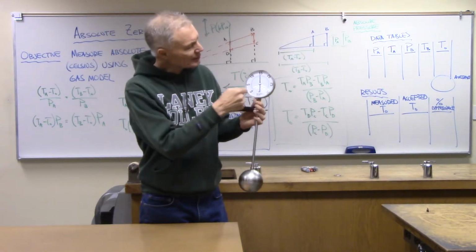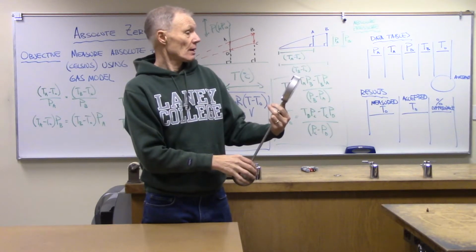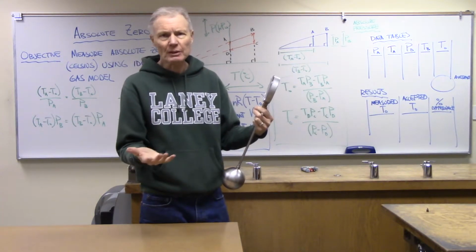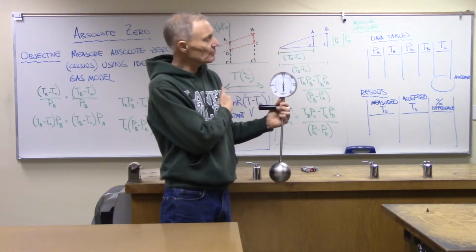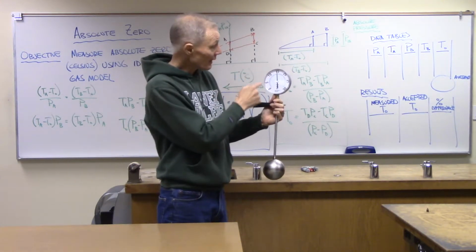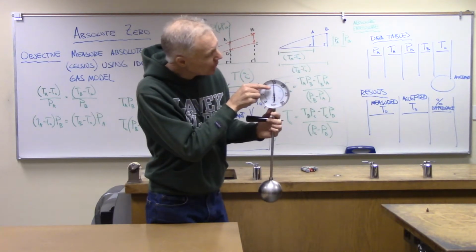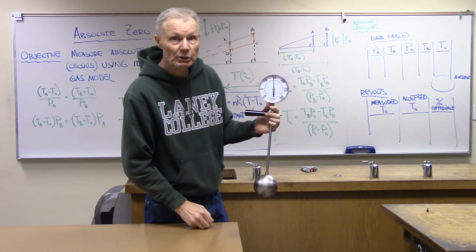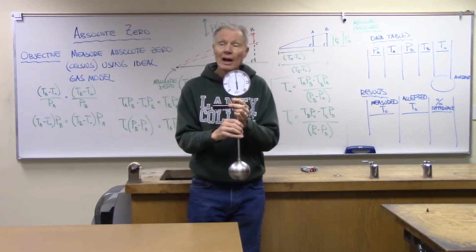So we have a pressure gauge built into this. Now, atmospheric pressure, which I'm guessing the room right now is pretty close to atmospheric pressure, would be about 100,000 pascals. Now the big numbers here are pounds per square inch. It's actually the blue smaller numbers here that are measuring pressure in kilopascals. And this is measuring pressure absolute.